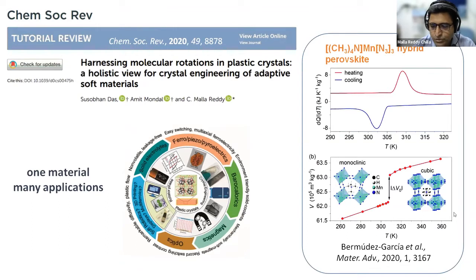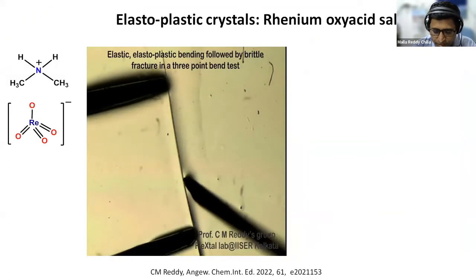And so, for example, if you look at some perovskite crystals, here you have a guest which attains orientational disorder before melting, and then you can actually use this energy change for cooling. You can use it as a solid coolant. So this can actually replace the liquid coolants that we use in refrigeration technology.